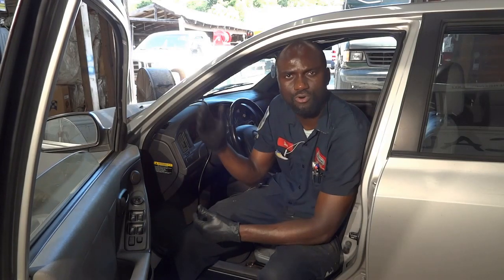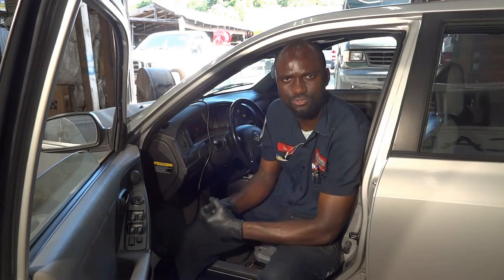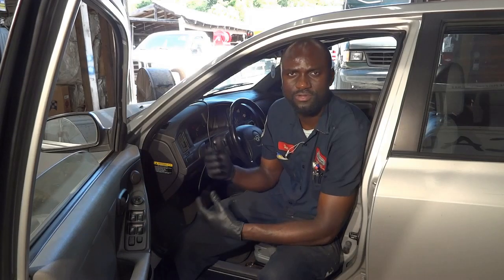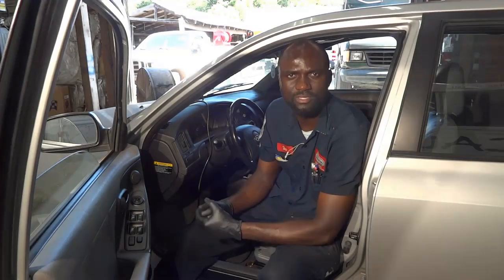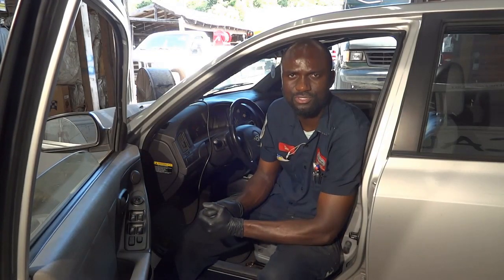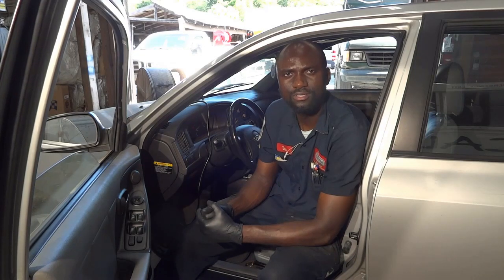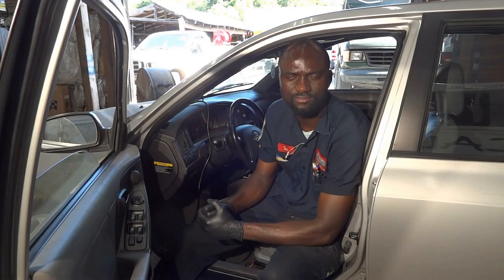If we cannot go over 35 miles an hour, then we're going to connect a scan tool to the vehicle to see if there are any pending codes in memory. If there aren't codes in memory, then we will maybe look at some data pads and get directions about how we can go to fix this vehicle. So now come with me so we can go on a test drive and see how this vehicle drives.